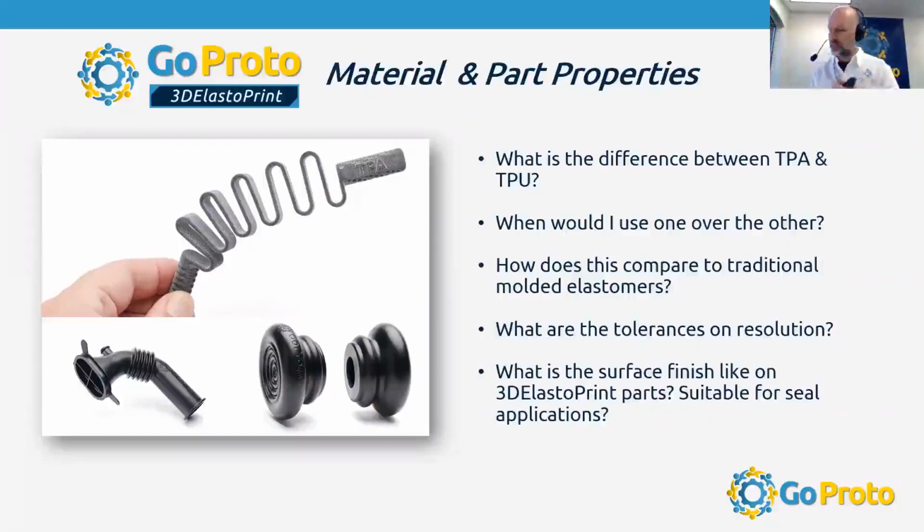It's incredibly capable. Being that this is powder based, we don't have to mechanically remove supports, which often put stress on the part and break it. Like with stereolithography, it can print thinner walls than multi-jet fusion can, but because you have to mechanically break off the supports, you often end up breaking the part because it's like tissue paper, like an uncooked lasagna noodle. Very important distinction. Because it's powder based, we can essentially just move it out, and you're not going to break the part, especially when it's elastomer and it can flex. So be thinking about anything that's less than about 1 millimeter. If you have specific questions about it, we can talk about it.